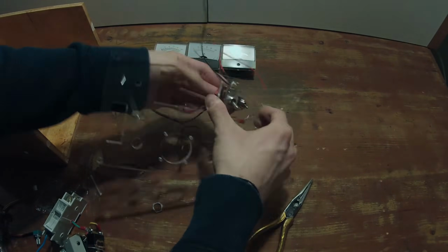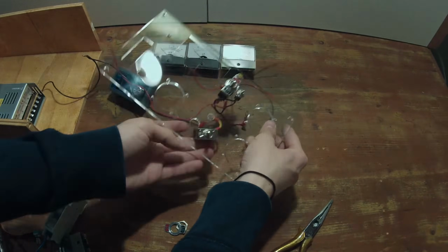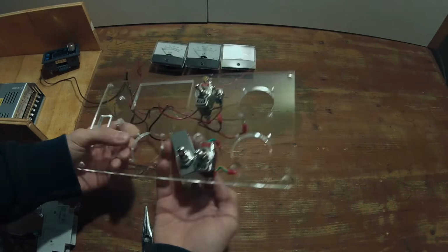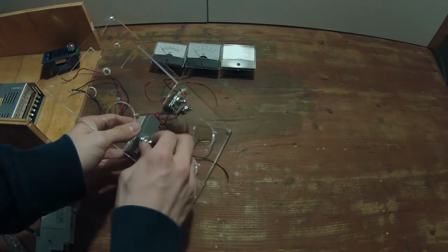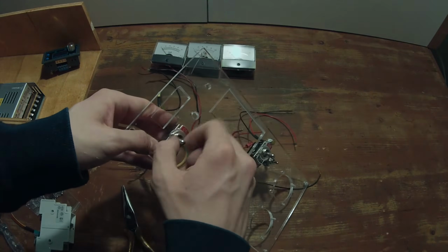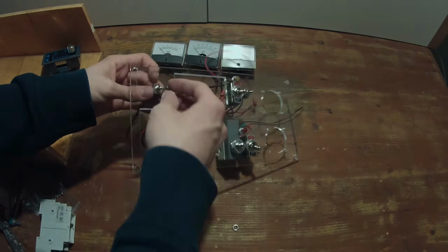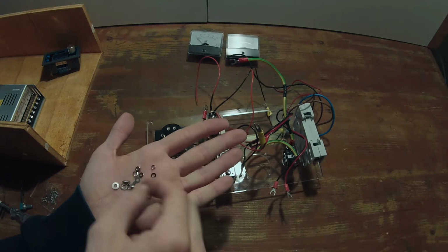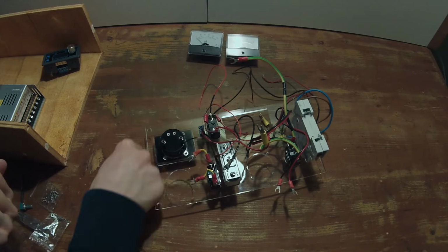That was the first ever prototype that I built. Anyways, in that prototype I used a positive high voltage multiplier, and in that case the voltage multiplier terminal was connected to the anode of the tube, that is the outside metal part, so it needed to be insulated from the rest of the world by being suspended on a big piece of plastic. Or I also used the book that you saw in the intro.